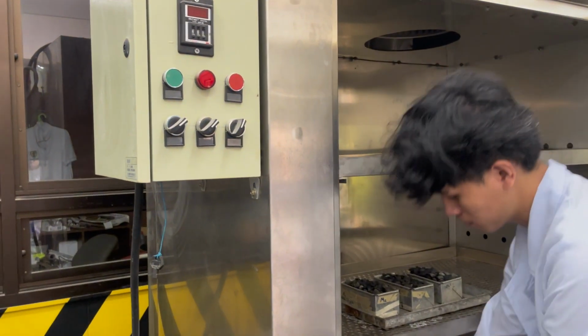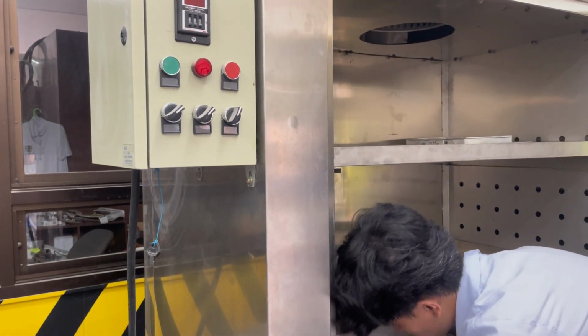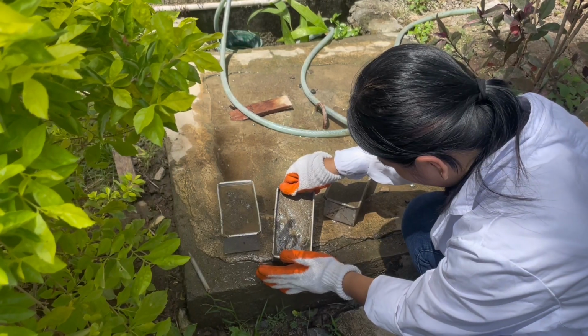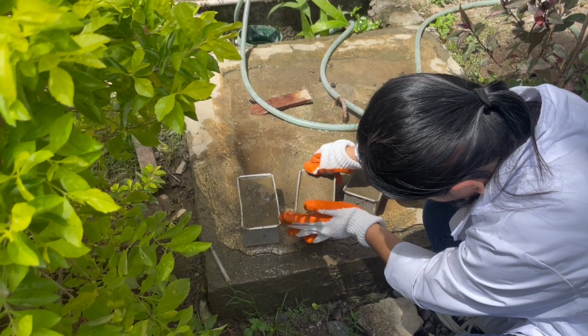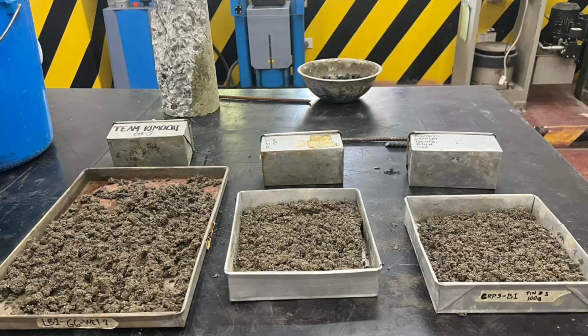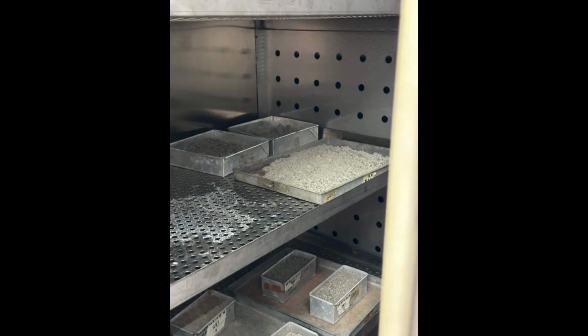Number 1, following the cooling period, we rinse the wet samples and immerse them in water at room temperature for 15 to 19 hours. Number 2, after immersion, we carefully remove the samples from the water, preventing any loss of the fines. Number 3, we spread out the samples on a flat, non-absorbent surface, occasionally stirring to aid uniform drying. Number 4, subsequently, we place the samples in the drying oven for a minimum of 24 hours. Number 5, post-oven drying, we record the weight of the sand as SSD or saturated surface dry mass.